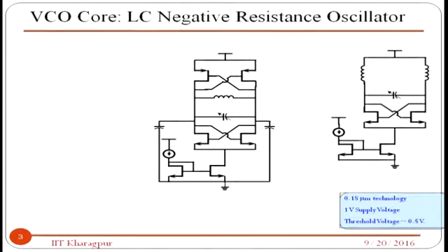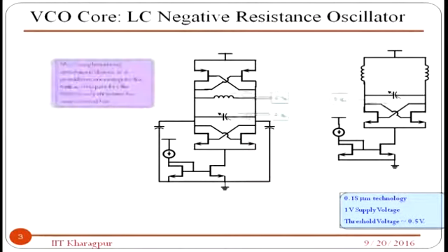So you understand this cross-coupled stuff can be done using an NMOS or CMOS cross-coupled pair facing an impedance, which is the tank circuit. This way you can handle 1 volt, either 1 volt across the two cross-coupled pairs, or 1 volt swing across just one such cross-coupled pair.